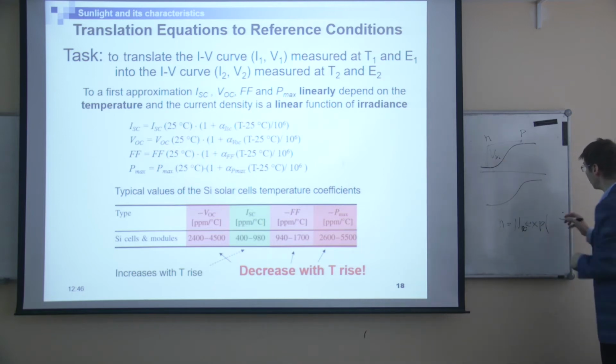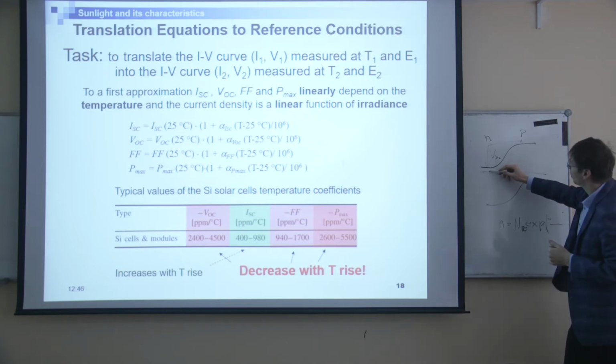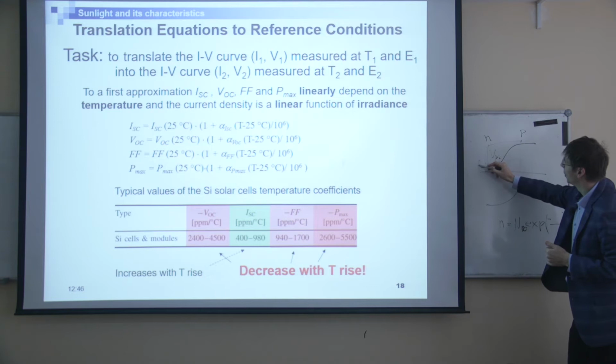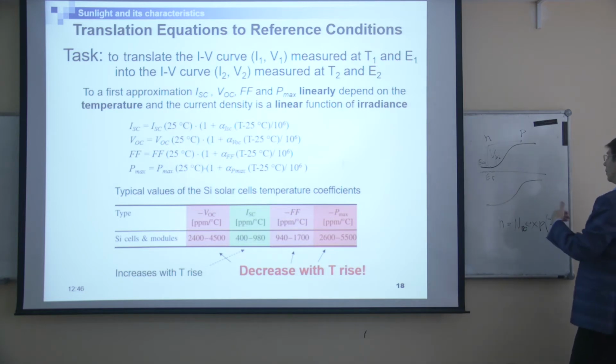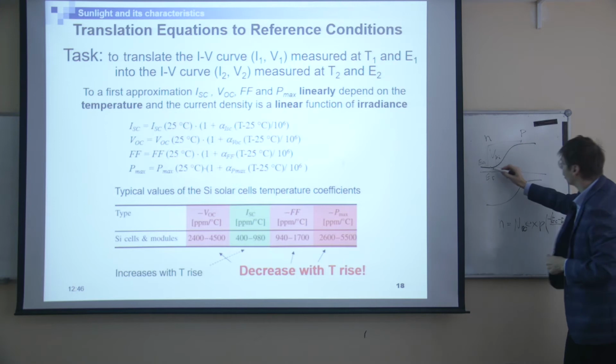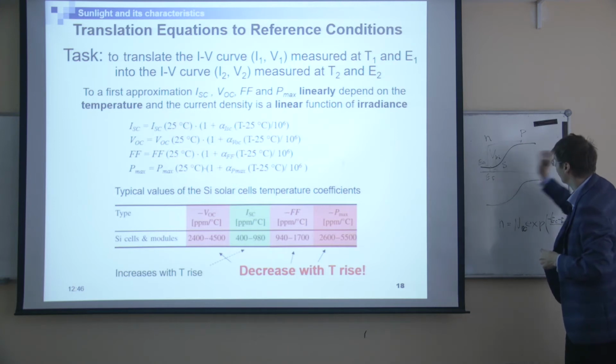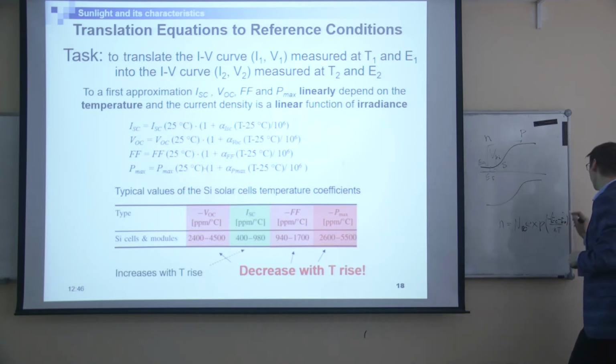Then you have an exponential behavior, and minus the difference between the position of the Fermi level and the nearest band edge. So it's the conduction band, EC and EF. So you have this minus difference, so it should be a negative value. You see minus the position of the Fermi level, so we can call it delta something, divided by kT.